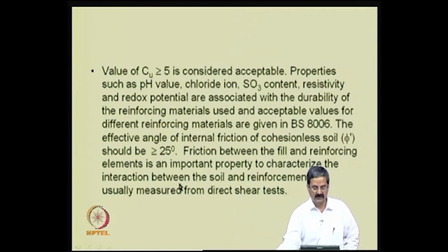Friction between the fill and the reinforcement elements is an important property to characterize the interaction between the soil and reinforcement, and normally we measure it from direct shear tests. As I told you, there are a number of tests that one can do. We discussed how it can be done. We have to subject it to 3 normal stresses and pull out or shear the reinforcement across it. So, you will get the result.